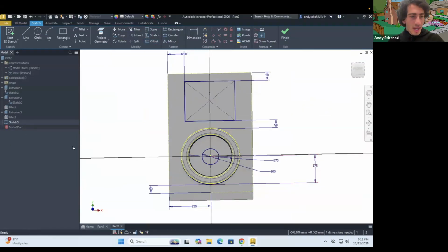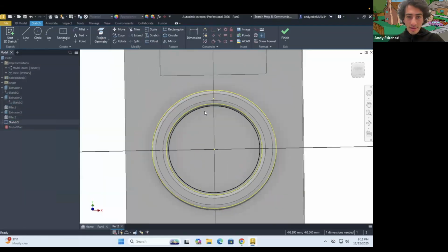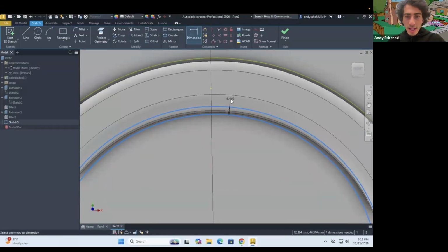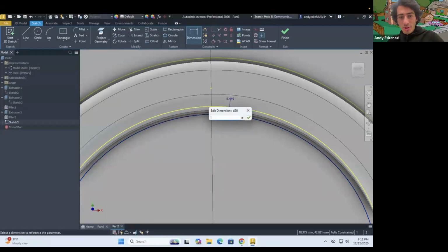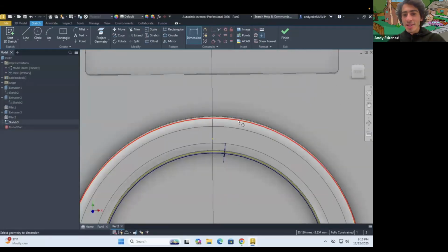Maybe I think I can, there we go. I can hide this stuff. It was starting to bother me a little bit, but I can say I want that offset to be maybe 2. Now it's minimal, right? And these lines, because they come from the previous sketch, are all fully defined. So that's why that one is already all blue. The same thing, I'm gonna click in there, then click on D, and we're gonna make that 2 as well. Good.